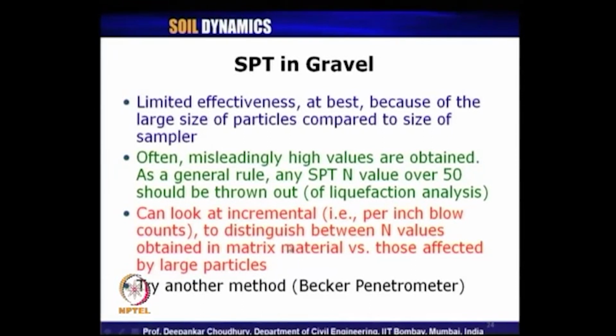To identify that, we should count per inch or maybe per centimeter how many blow counts are coming. That will give us the confidence whether it is truly a very stiff soil where liquefaction analysis is not required, or it is just at a particular location, because of the presence of large particles, that there is suddenly a high N value. In that case, if you discard the liquefaction analysis, that will not be proper.